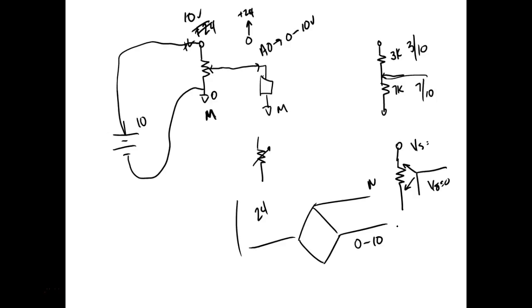So that's an AC. This is a DC, DC, DC, which means what? I have to power it with 24 volts, right? You understand? The inputs are DC, so they're going to be DC inputs, and then it's going to be DC outputs, right? That guy is what we call an AC DC relay. So that means I've got to put 120 volts on that thing.